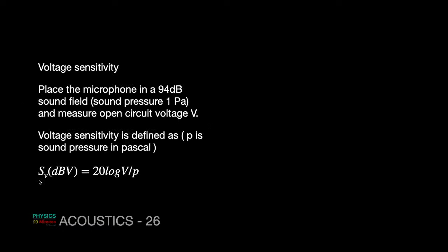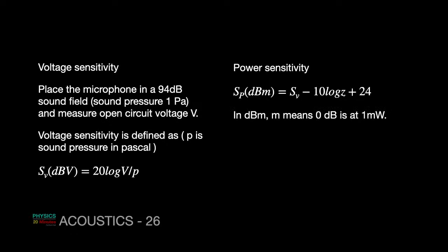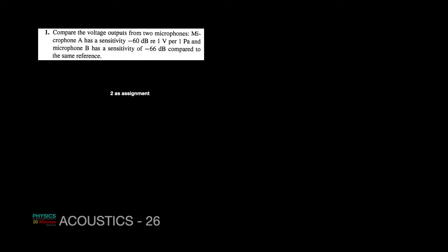This is voltage sensitivity, 20 log V by P. This is the developed voltage. This is pressure, which is in Pascal. And for the power sensitivity, once you get SV, you can calculate SP in dBm, and do both calculations.